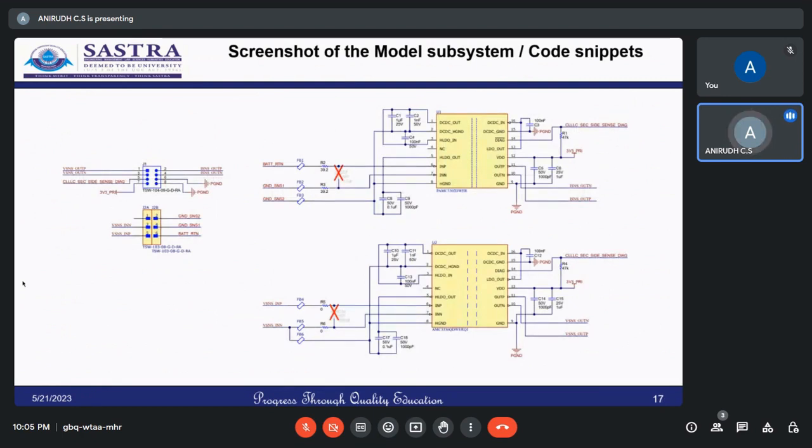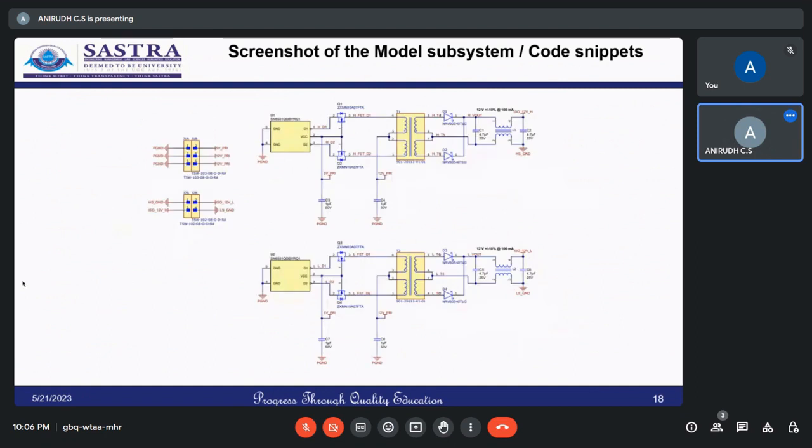And here we can see the U1 and U2 subsystems are converting the CLLC secondary side parameters to battery side parameters and ground parameters. And U2 converts CLLC secondary side parameters to VSNS input parameters, which is the voltage source input parameters. This shows the bias voltage and the effects of bias voltage on the U1, U2, and T1, T2 transformers.